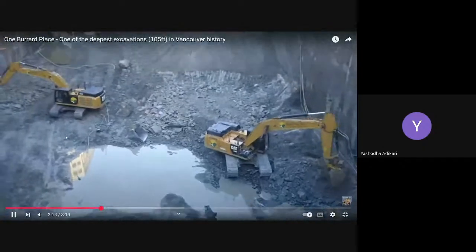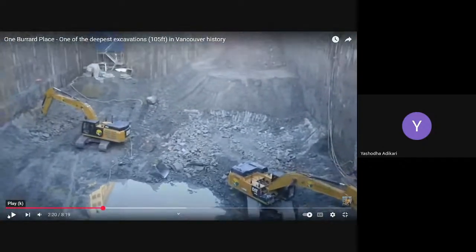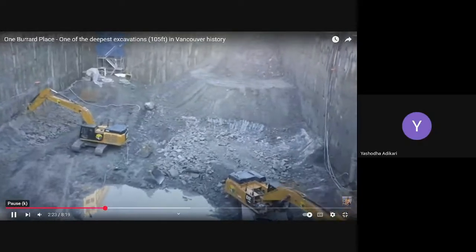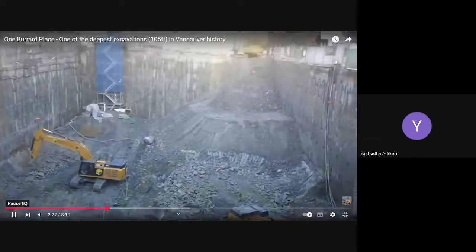When we are doing this excavation activity, sometimes we have to face another challenge: water. When we are doing deep excavation, going level by level, we have a challenge from the groundwater level. In a case like that, you have to allocate some laborers, machinery, or sometimes technologies to remove the collected water from your excavation. It is also a challenge to work in deep excavation, and it happens because of the groundwater level.